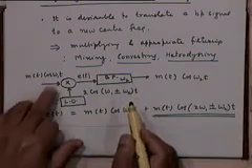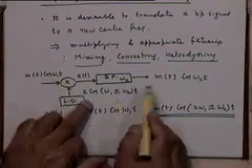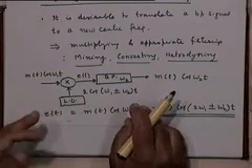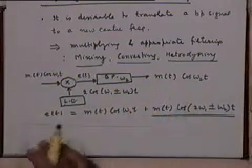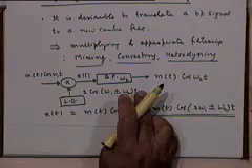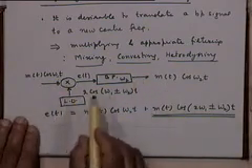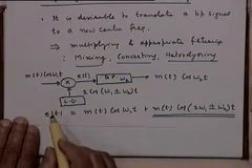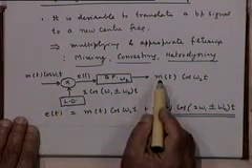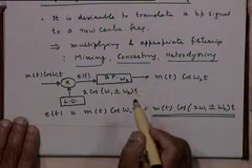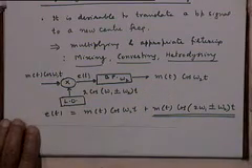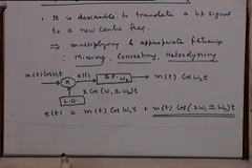So for every frequency that it is supposed to translate, there is also what is called an image frequency, which it will translate to the same frequency. Not only will it translate omega 1 to omega 2, it will also translate omega 1 plus 2 omega 2 to omega 2, right? So omega 1 plus 2 omega 2, that frequency is said to be the image frequency of omega 1.